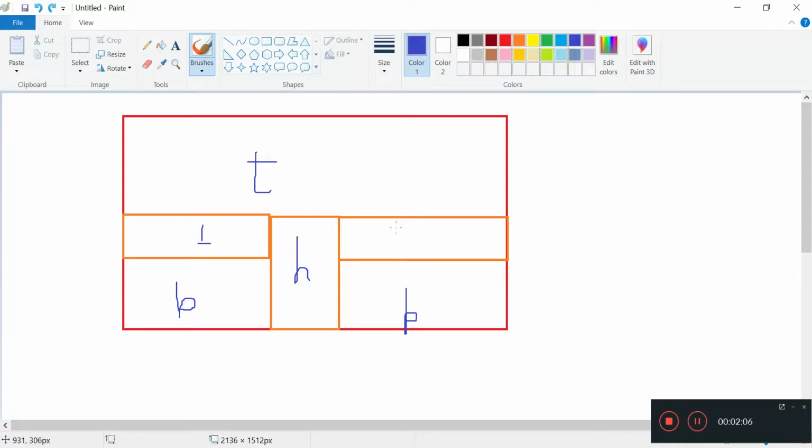Now, let's try again. Okay, so how did we actually define this? We used topoSet, and we used a box. We used a simple box with some coordinates to say, hey, I want to select this group of cells, and this group of cells should be called the heater zone. So that's why we have this box that selects a certain set of cells in the blockMesh, and then we call it the heater cell set. Then this left solid is another cell set, this right solid is another cell set, top air is another cell set, bottom heater another cell set.